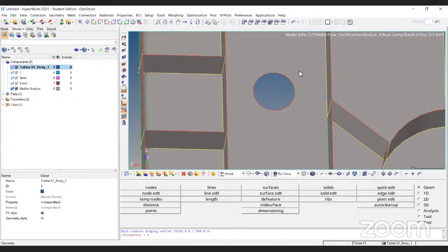That means I am going to represent my FE model, if it is a bolt hole, with one more washer set of elements. It represents M8 or M12 or something like that. What is the diameter of this one? According to the diameter, I am going to create the washer. How to create the washer?